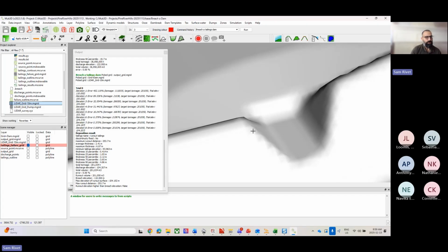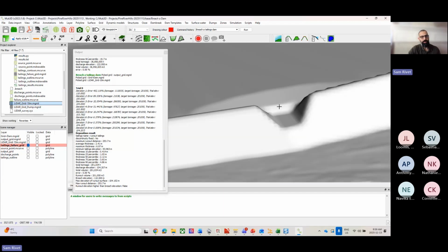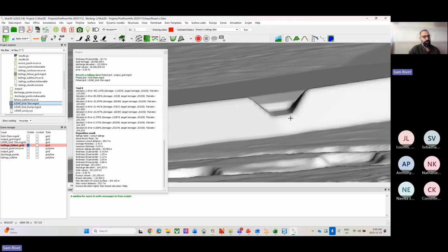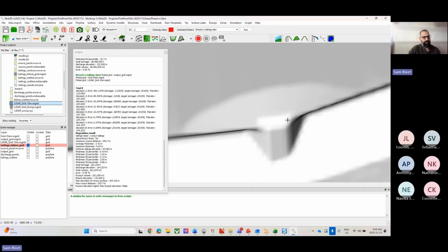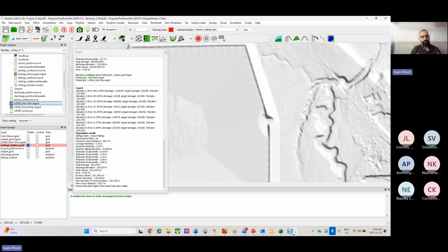The only difference here between fail a dump and this function, breach a tailings dam, is we get to define different slopes for material within the TSF versus the embankment structure material. So it fails differently. This fails at 3-to-1, the cross section. This failed at 5% based on what we input. And having that option to pick that additional surface, the grid plus dam and the output grid with the tailings merged in, allows us to do that.